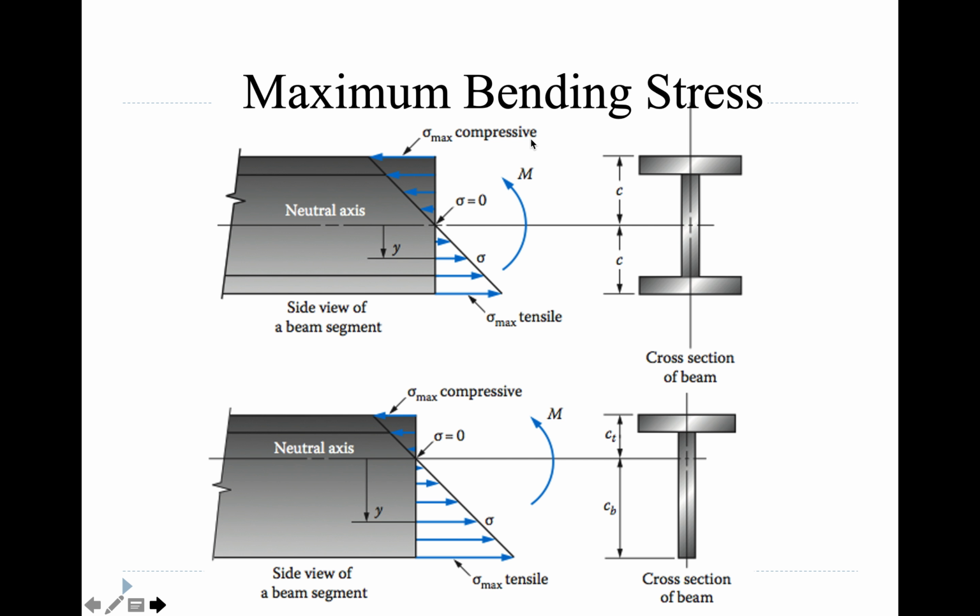Okay, so here it is visually. Just like in the torsion lectures, where the maximum torsion was occurring at the outer edge, the fibers as they're referred to in this lecture, the maximum bending stress is also there. Here it is plotted in picture form, just like I described in the second slide. The maximum is at the outer edge. This is what I mean by the fiber. This is what the textbooks mean by the fiber, the outer edge of this cross section. This is the beam going long ways, and this is the cross section. This is what it looks like if you turn it.